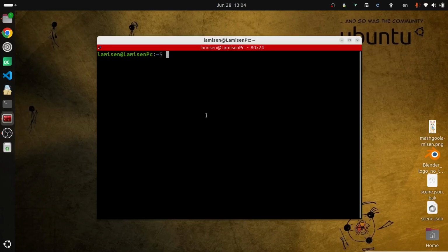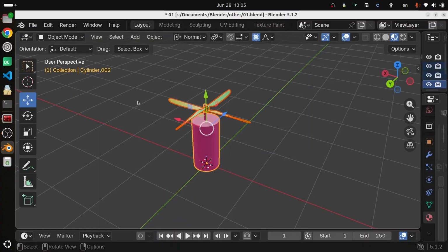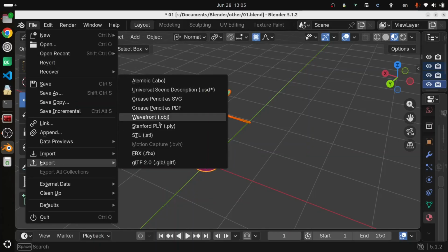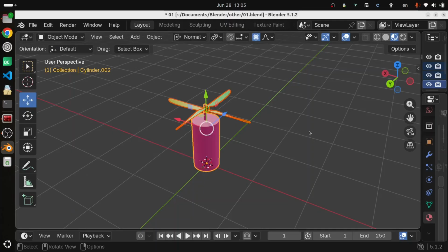Have you ever installed Blender using a snap command? Sudo snap install Blender. Launched it. Built an awesome model and then you realize you were stuck. You go to File, Export, and nothing. There is no Collada option anymore. It's really frustrating, especially since you need that DAE file to get your model into Gazebo.